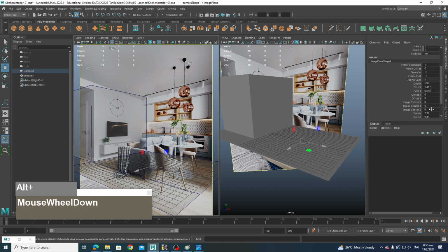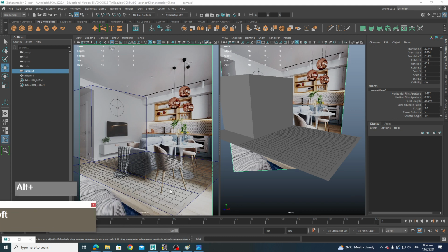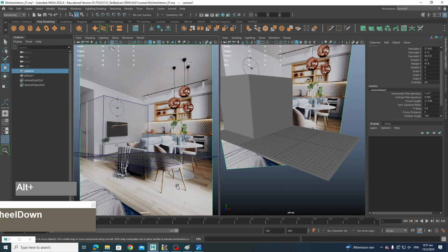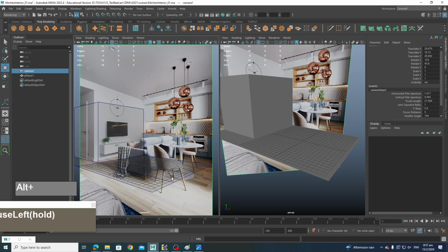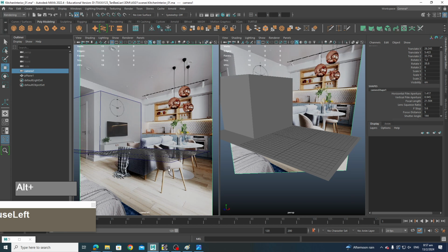Okay, so right now the camera, let me see the focal length. Let me select the camera. I'm going to check the focal length. This is correct, 21.54, because this is the value that I got when I was playing with fSpy, but it seems that right now the focal length could be slightly off, or my orientation is wrong. Another thing is it could be the distance also. So right now I'm pulling the camera back a little bit, and I'm checking the perspective to see whether it matches or not.